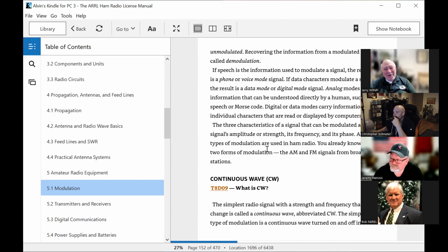Well, okay, I'll whistle it. Da, dit, da, dit, da, da, dit, da. Take that carrier wave and make it do something. What I'm sending, da, dit, da, dit, is telegraphy. The old telegraphers would recognize that as the letter C. If I do da da, da da, da da, da da, that is Q. So I'd be sending CQ. Just by turning it on and off, I can make signals known.